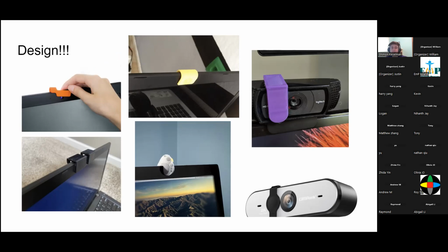So when I look at this from a CAD point of view, what I see is this big front plane. And so I'm thinking that what we can do is make this a sketch and then extrude this out to make it 3D. So let's start by doing that.